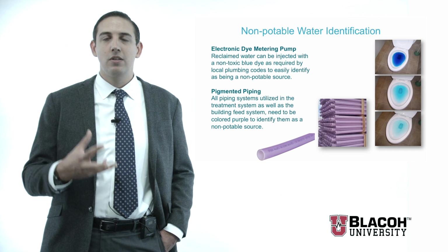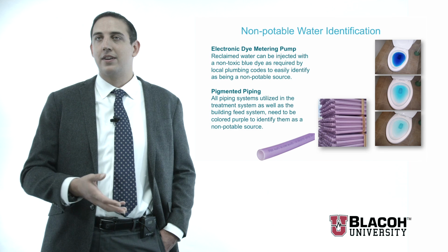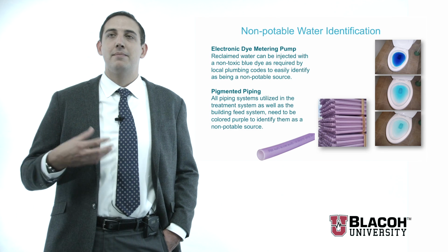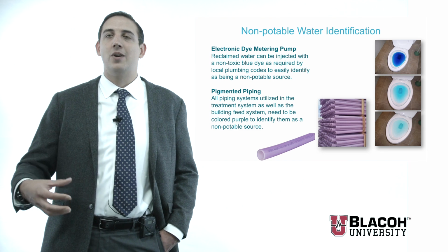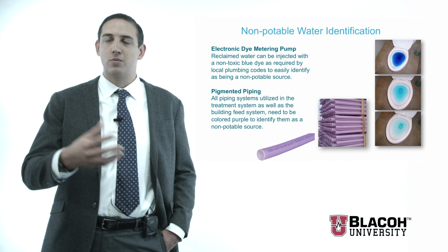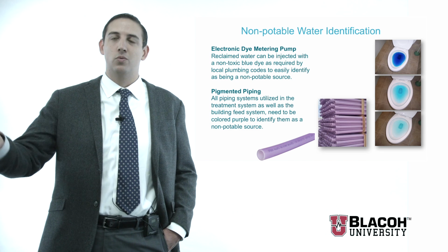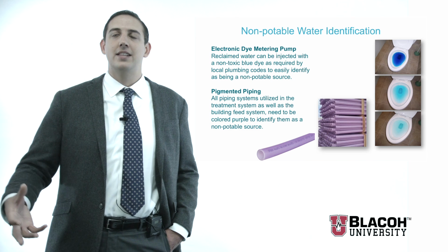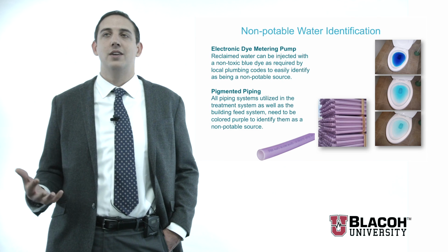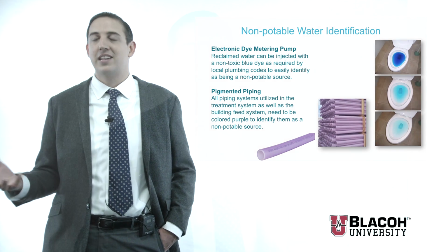And the reason they do that is not because anybody's going to actually drink out of a flushing fixture, but say 10 years from now, when somebody taps into a line, maybe runs into a water fountain, they turn it on, they start shooting blue water out, that gives them a heads up that this water is probably not ideally lined to a drinking fountain. It actually did happen at a high school in the Midwest about 10 years ago. They actually ran the blue line right into it.